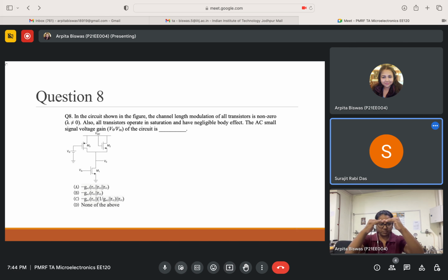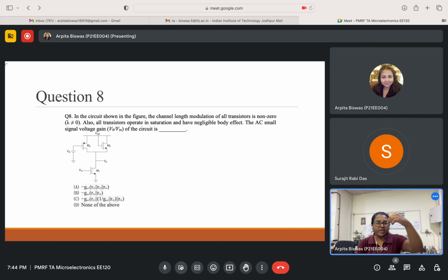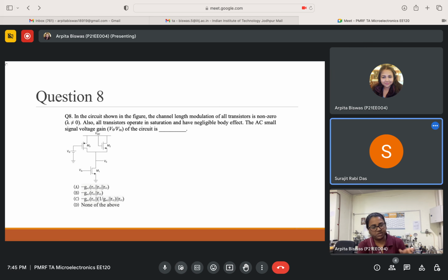It has this type of diaphragm, and this is the total silicon wafer. When pressure is given, the wafer is bent, so the electrical property of the material changes, and we find out how the resistance or electrical property changes.